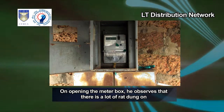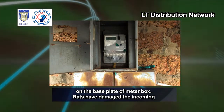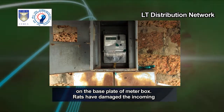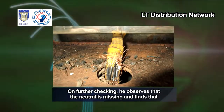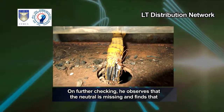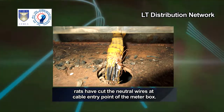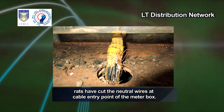On opening the meter box, he observes that there is a lot of rat dung on the base plate of meter box. Rats have damaged the incoming control cable at the entry point. On further checking, he observes that the neutral is missing and finds that rats have cut the neutral wires at cable entry point of the meter box.